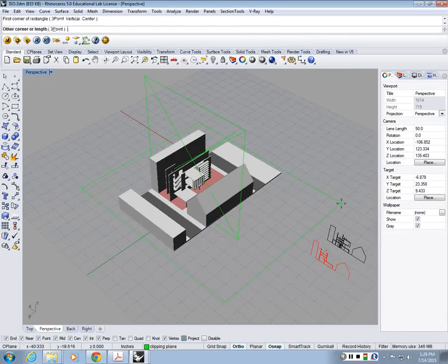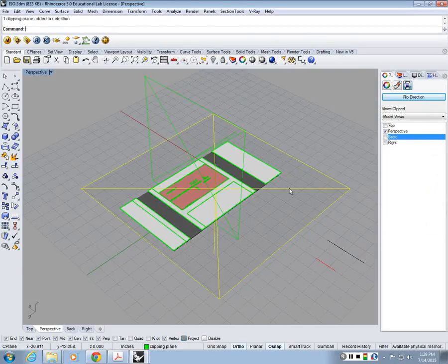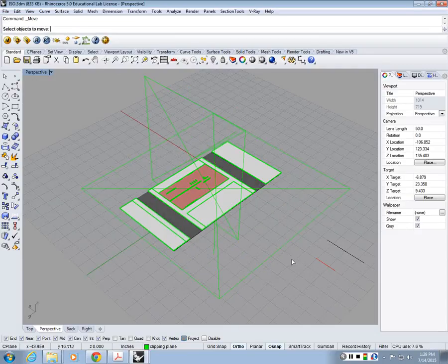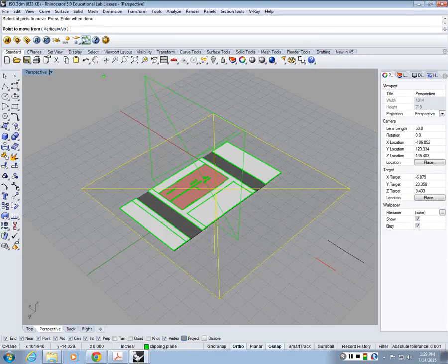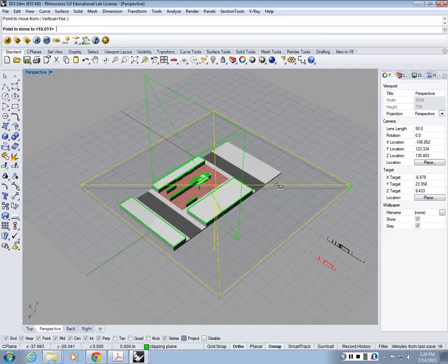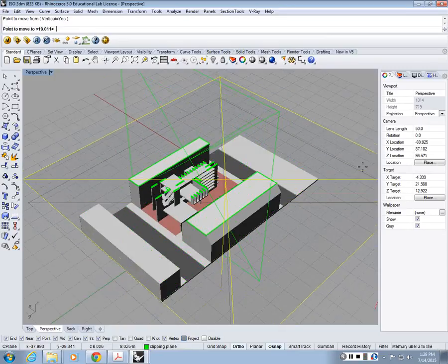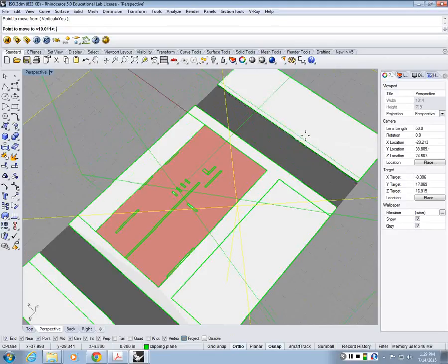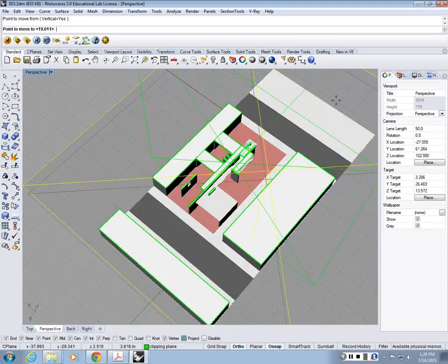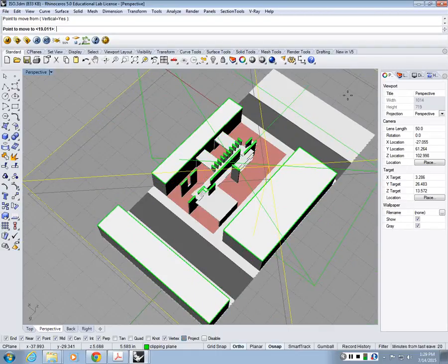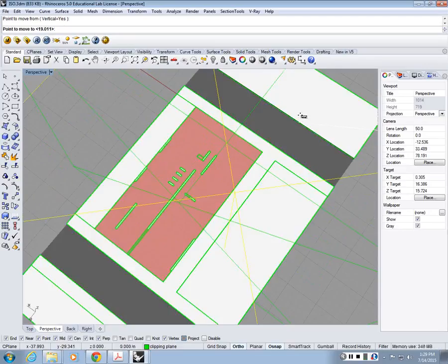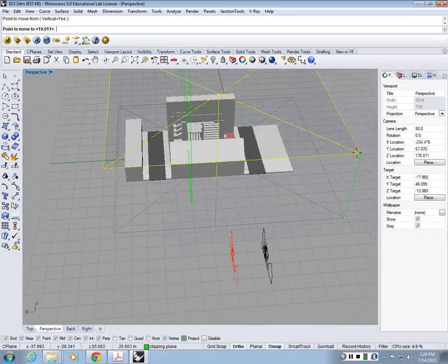You could also draw a rectangle. So just draw this rectangle, and then you want to move it up. So I type in move, and then I'm selecting the vertical option so that I could just start rising above and see where I want to cut this building. So I want to find a nice point, right? We also don't want to cut it closer to the ground so that when you draft it you get a lot more geometry, surfaces, like details to show, basically, maybe stairs as well. So again, when you're drawing plans, you don't want to cut through the steps, right? So where I want to cut through is somewhere in the middle.